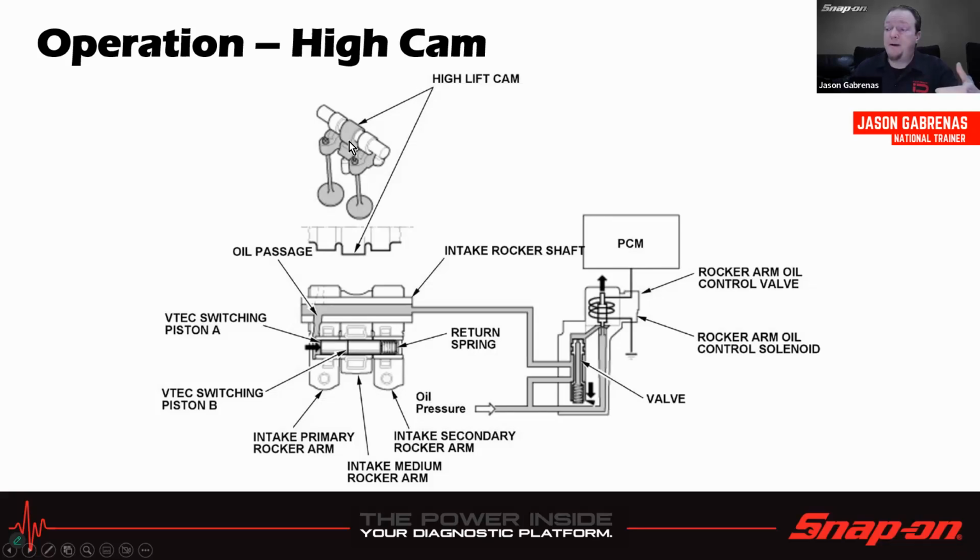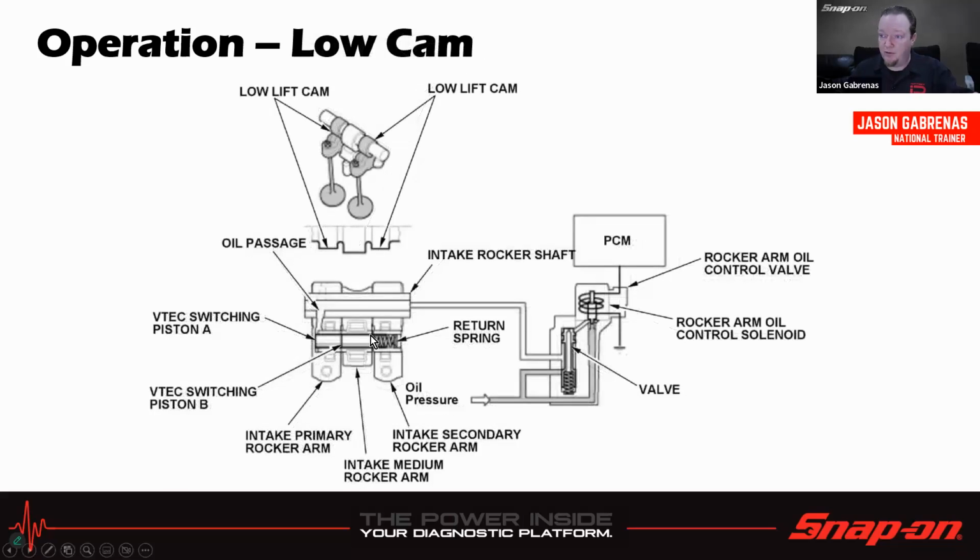So when it's just sitting there off, let me back up a slide. When it's sitting there off, this pin in the middle isn't doing anything. It's just sitting there, and that high lift cam is still obviously going to be turning, but it's just kind of flopping around in the breeze. It's not directly connected to a valve.